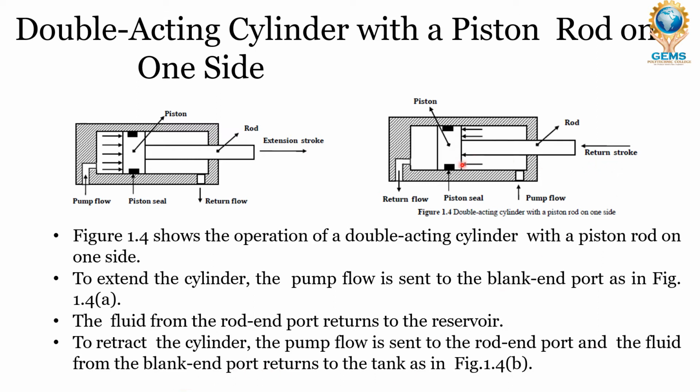So in order to do the return stroke, here there is no gravity motion or spring option. The return stroke is also done by the hydraulic fluid only. The pump sends pressurized fluid through the rod side, and from the blank side, that oil will return to the return tank.